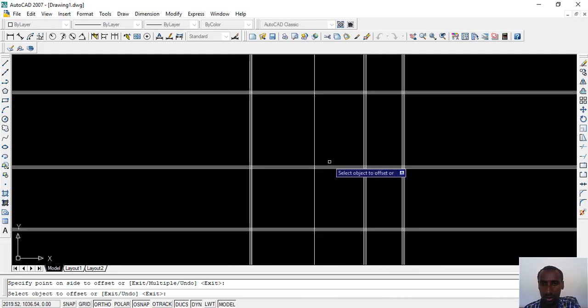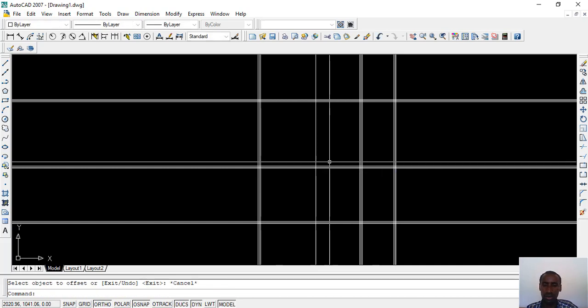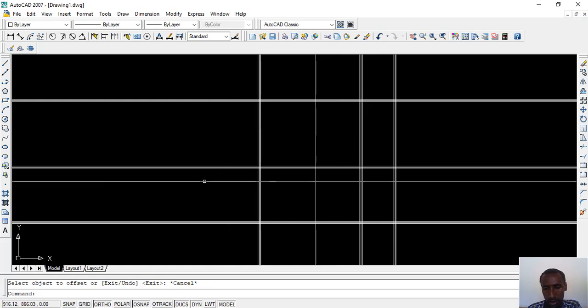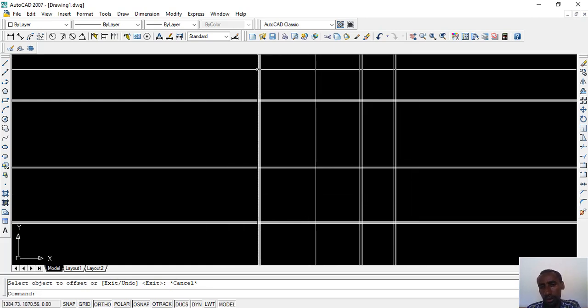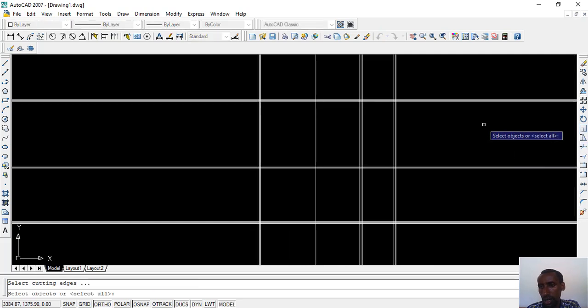So what shall I do now? I try to develop the boundary. Let me remove this one, that is, let me use trim. You have to order trim, click, normal click, then right click.